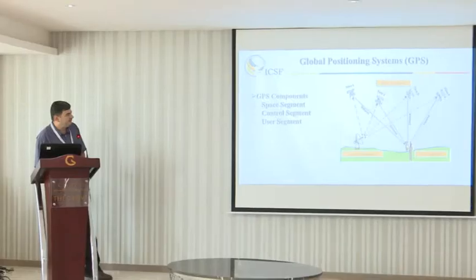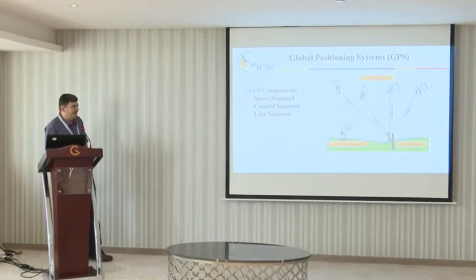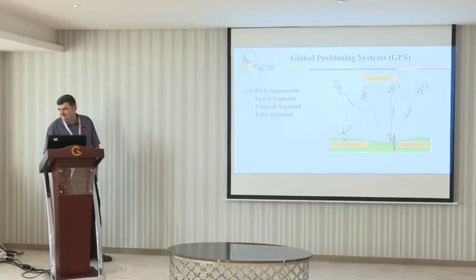For monitoring structures and deformation, GPS provides position over time, every second, every epoch, every minute, whatever you want to call it. So this provides you with a model over time, and this gives you a continuous check of the situation of the building, the stability of the building.